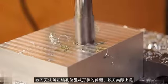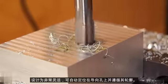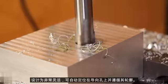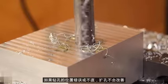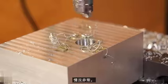Reamers are actually designed to be very flexible, self-centering on the pilot hole and following its profile. If the drilled hole is in the wrong location or isn't straight, reaming it won't improve the situation very much.